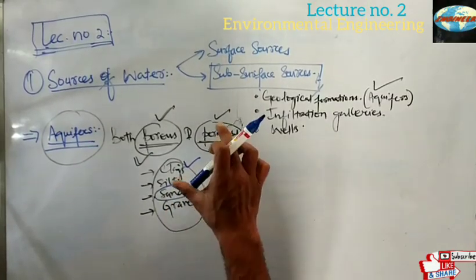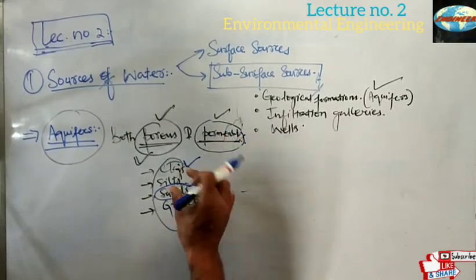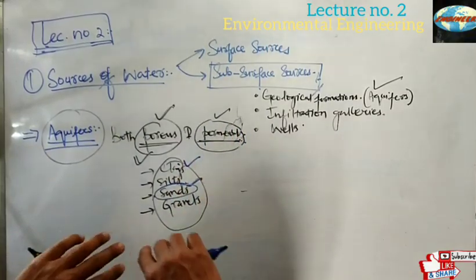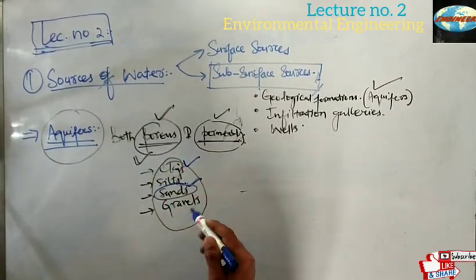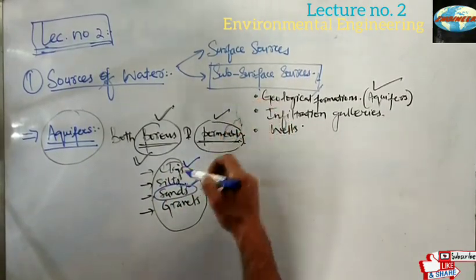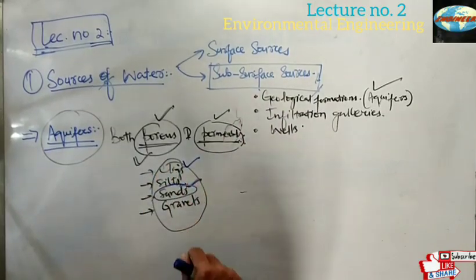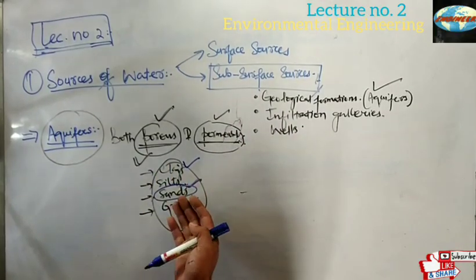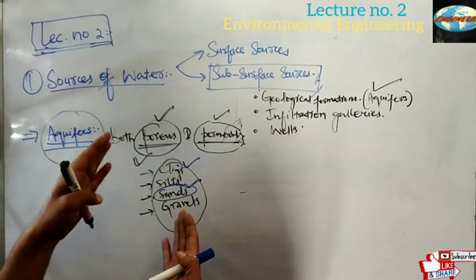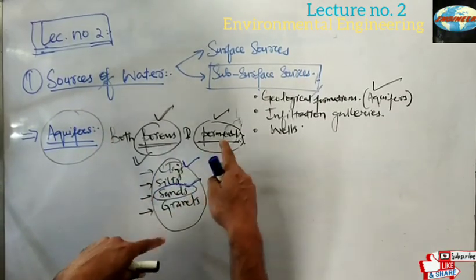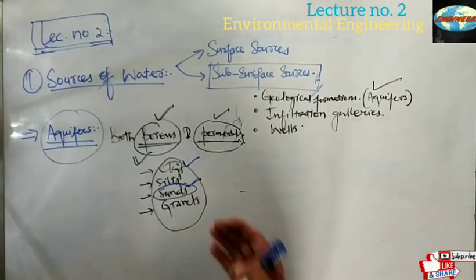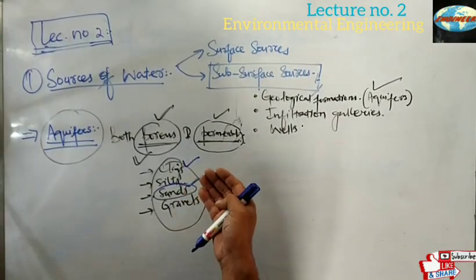They have high permeability if you compare them with the clay, because we don't have absolute values. We can compare different types of soils over here. Now sands have higher permeability than clays, but they have less porosity. What I can say is their water storage capacity is lesser than clays, but they can actually drain out water. You can actually draw water.